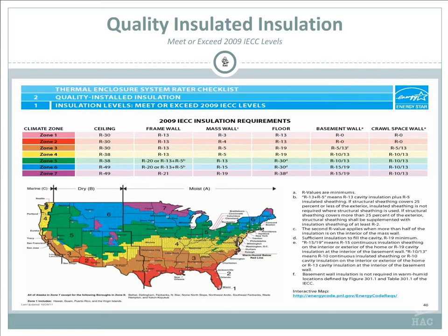Floor insulation, 13. You get an R38. It's going to be hard to make an R38 on your floor. You're going to have to use foam board plus insulation, probably. Again, these are the minimum requirements.